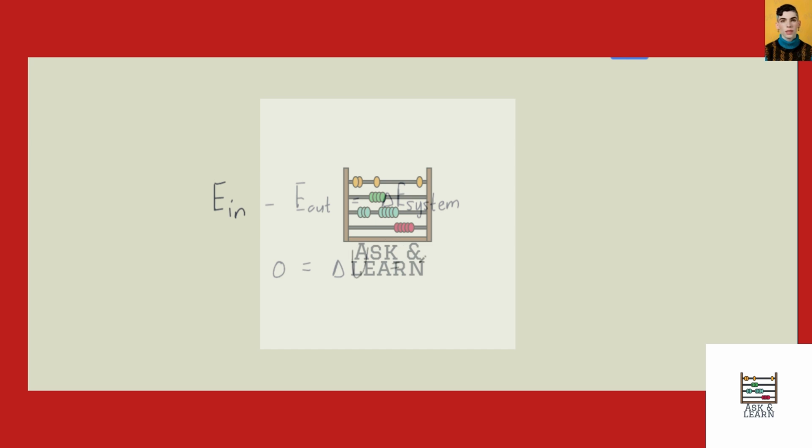And we have a change in internal energy, delta U, and this is equal to m times the specific internal energies, little u2 minus little u1. Remember, W, Q, kinetic energy, and potential energy are all zero here. So we can see simply that the internal energy per unit mass in state 1 is equal to the internal energy per unit mass in state 2. So that's our energy balance equation.